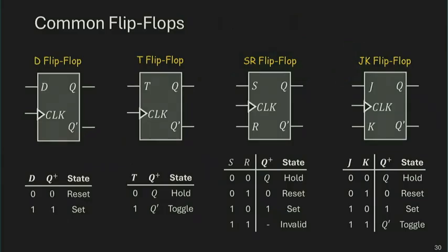And these are the 4 flip-flops that we will deal with, and these are also the most common flip-flops. We have D flip-flops that support 2 operations, set and reset. So D equals 0 is reset, D equals 1 is set. We have an SR flip-flop, again, supporting the 4 operations just like before. So the definition of an SR latch and the SR flip-flop are really identical, except that the latch is level sensitive, the flip-flop is edge sensitive.